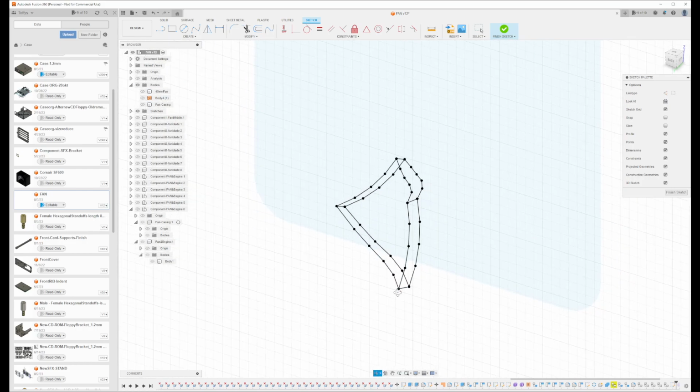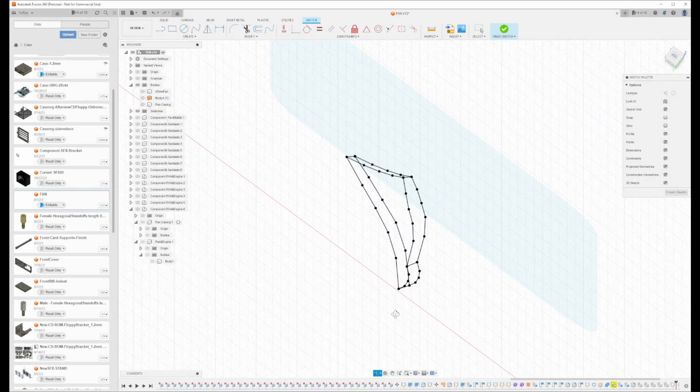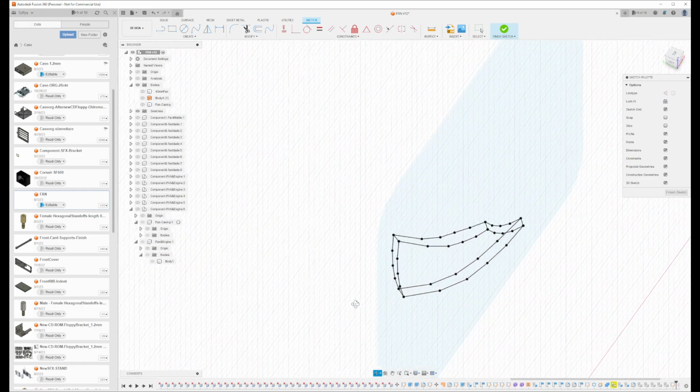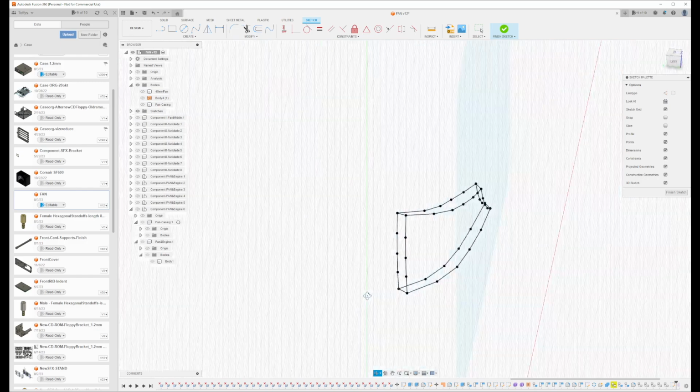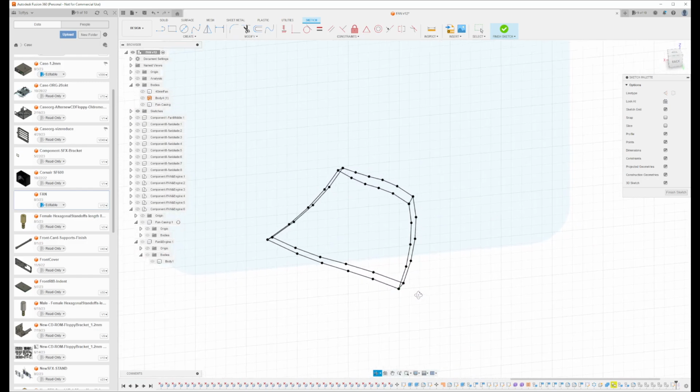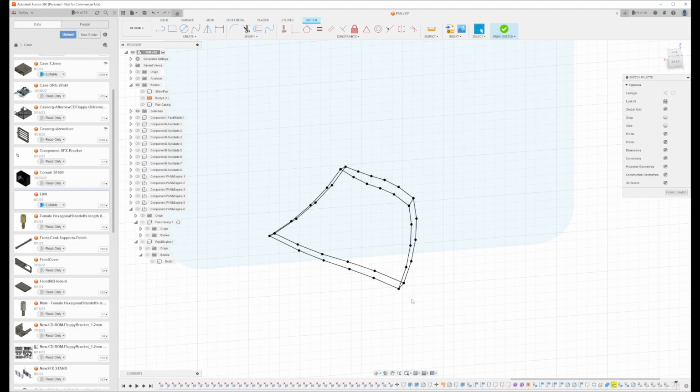There. Now you can see that there exists a 3D space. Now, to make this into a solid object, you have to give it surfaces. But before that, I prefer to simplify the sketch a little bit. So what I'm going to do now is make everything into dotted lines. And I still operate within the 3D space.